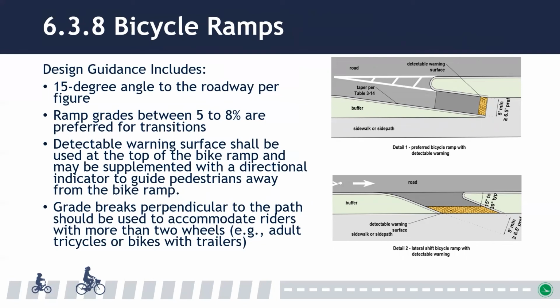It is common to use bike ramps when approaching roundabouts, at interchange ramp crossings, or at high conflict zones, such as weaving areas or high turning volume intersections. In these situations, the bike ramp serves the purpose of allowing bicyclists to avoid sharing travel lanes with motorists.